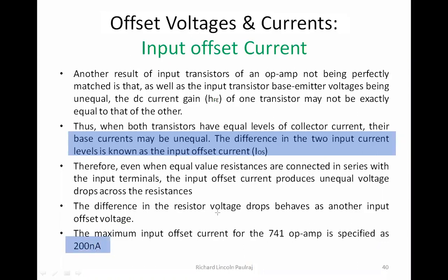This is also from the data sheet. So ultimately, the data sheet is very important, where we get to know how much is the value of input bias current, what the levels of output offset voltage are, and at what temperature I should operate. Do you think operating in all temperatures gives us all ideal outputs, students?